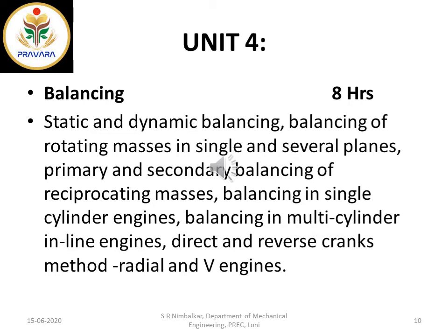Now this balancing is done in various applications. First is the rotating masses. This rotating mass may be in a single plane or in several planes. All of you know the inline cylinders with pistons. If you see the pistons of the inline engine, the crank of that inline engine is rotating, and the masses are rotating in various planes. This is an example of rotating masses in several planes. So single plane and more planes, that is several planes.